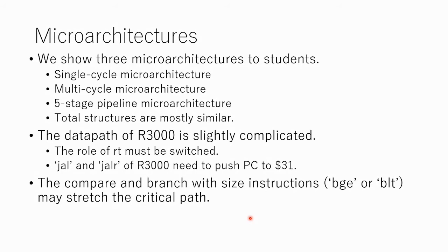Jump and link and jump and link register of R3000 need to push a special register, register 31, for storing the program counter.